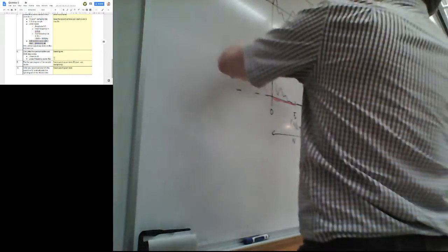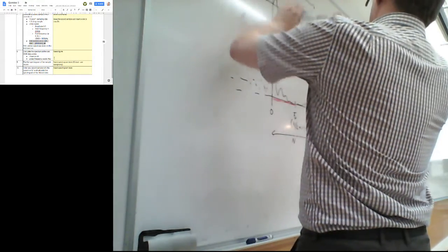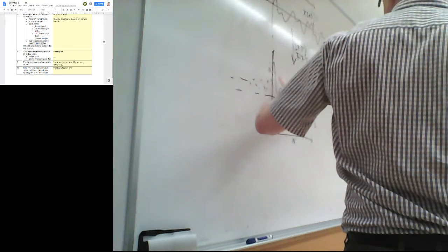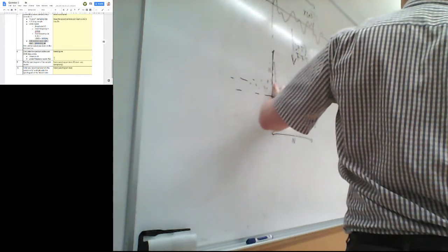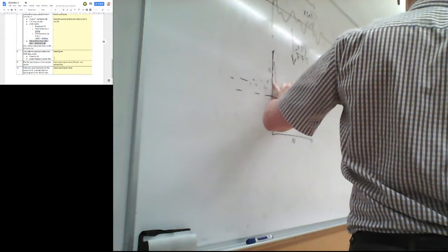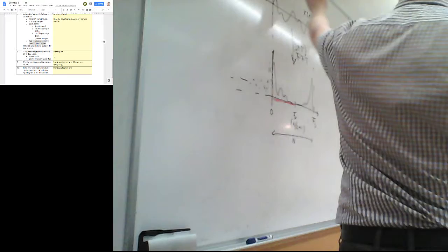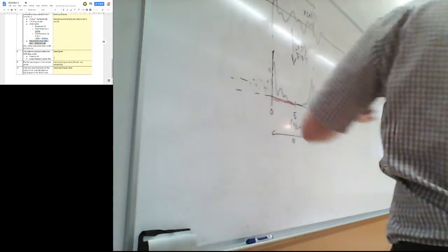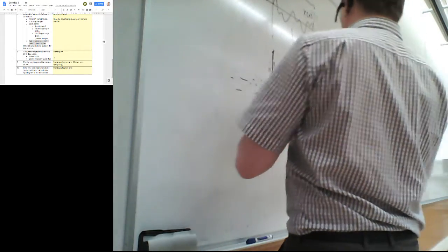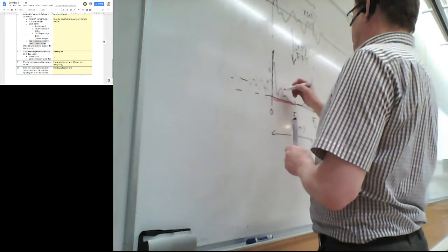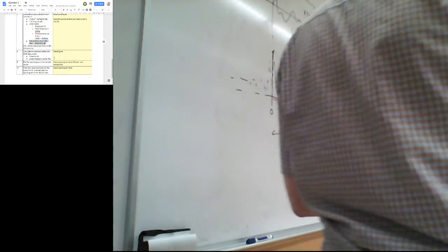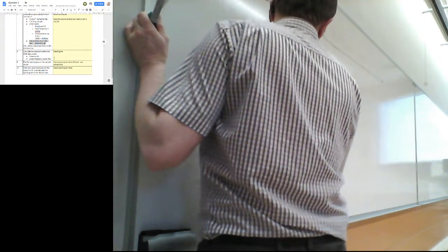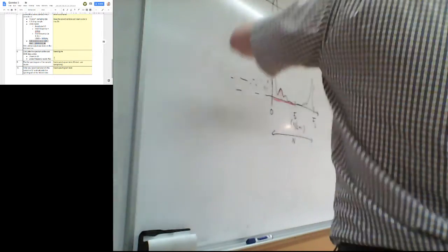So the real spectrum is actually convolved with the Fourier transform of the box, meaning the sinc function, which basically widens those peaks. If you have one single pure frequency, in reality it goes wider when you have that kind of square-shaped window.